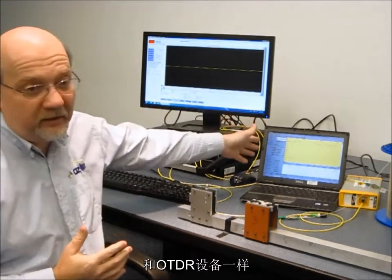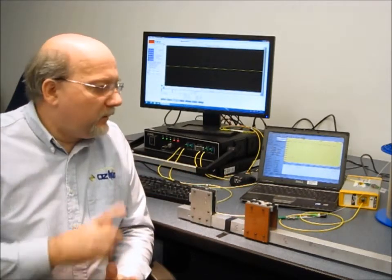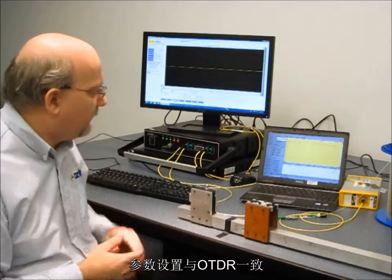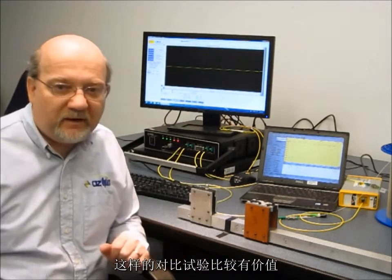just like with the OTDR system, we're using pulses that are 10 nanoseconds in length, which will give us a resolution of about 1 meter through our fiber. We are also doing averaging. We're averaging over about 10,000 samples. Again, we're doing this in order to have an accurate signal with low noise. So the conditions are similar to what's being done inside the OTDR. So this will make a good side-by-side comparison.